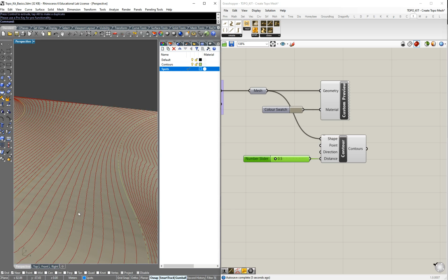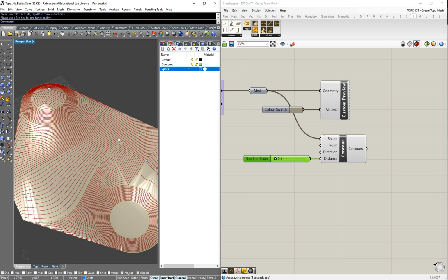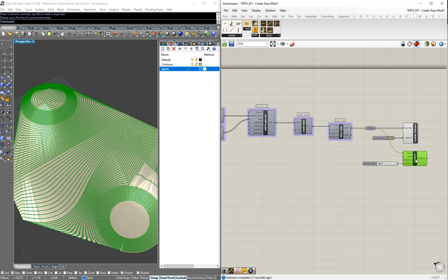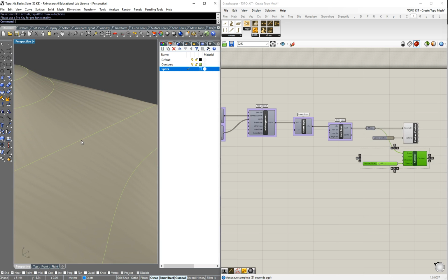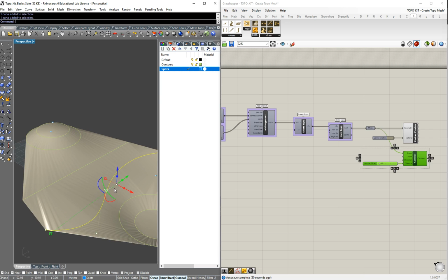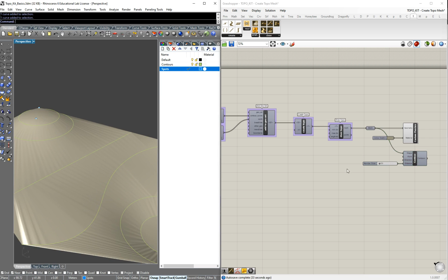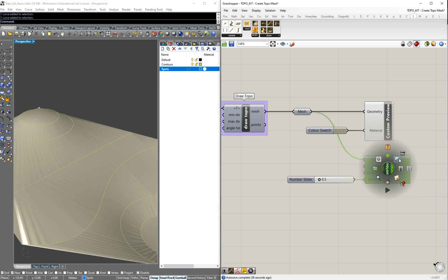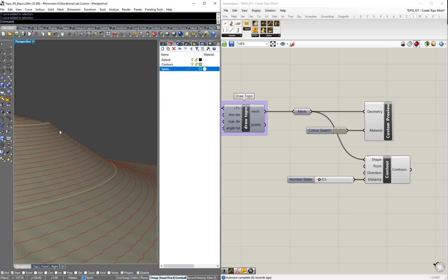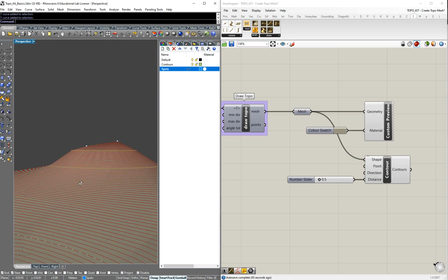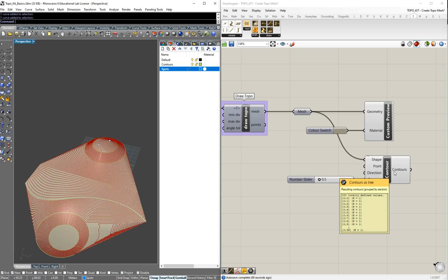These are contours that are derived from the mesh or the topo mesh you just created. So it is very interesting. Here there is a concept of spatial interpolation. So how this works is you have 3 or 4 points, and the values are interpolated between a specific point in this line and specific points in this other line or curve. But once you have created the mesh, you can generate these contours or breaklines to identify the different subset of contours you generated for the topography, and use them, export them, or bake